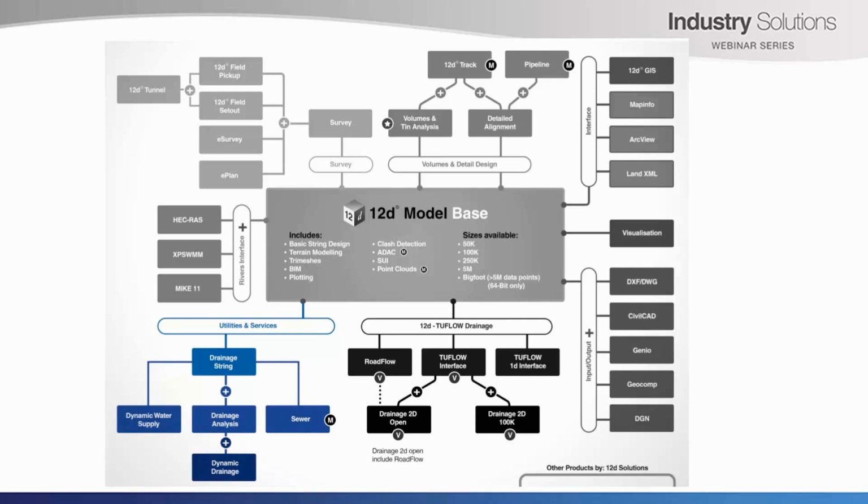We also have a dynamic water supply module. This performs hydraulic analysis and models the water behaviour in pressurised pipe networks consisting of pipes, junctions, pumps, valves, storage tanks and reservoirs. This module uses the EPANET engine.